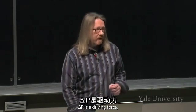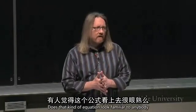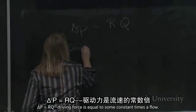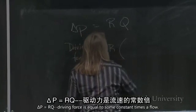Delta P is a driving force. Pressure difference is a driving force. It's what causes the flow, and the flow is what results from that. So delta P equals RQ. Does that kind of equation look familiar to anybody from their high school physics? Have you ever seen an equation like that? Delta P equals RQ. Driving force is equal to some constant times a flow.